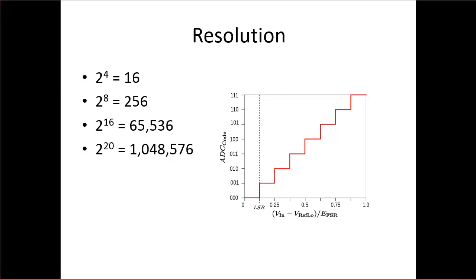Okay, so when you choose your analog to digital converter, or in the case of industrial control systems, a lot of times you just buy an analog input card for a computer, and you'll choose a 20-bit resolution input card. Most of the time you'll get the card for the computer and you'll know what the bit level is. So I want to talk a little bit about the concept of quantization error.